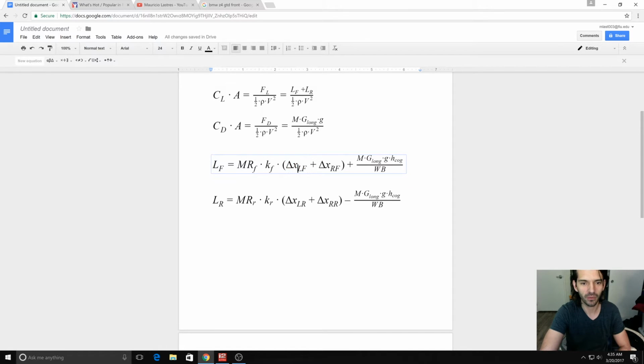the suspension traveled. But that's the suspension travel added for the two front springs, because there are two springs in series. No, well, they're parallel. Sorry, two parallel springs, the left front and the right front, and springs in parallel are additive. So we'll do it this way.